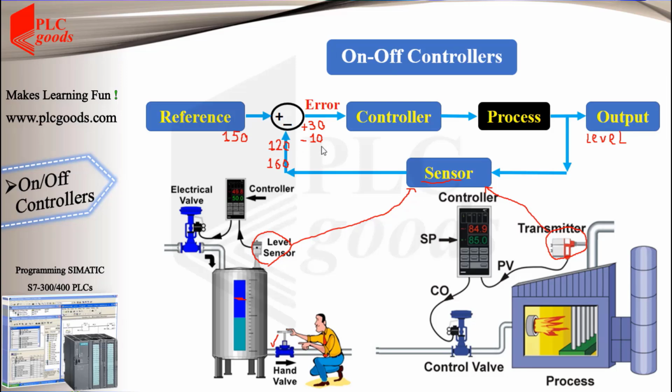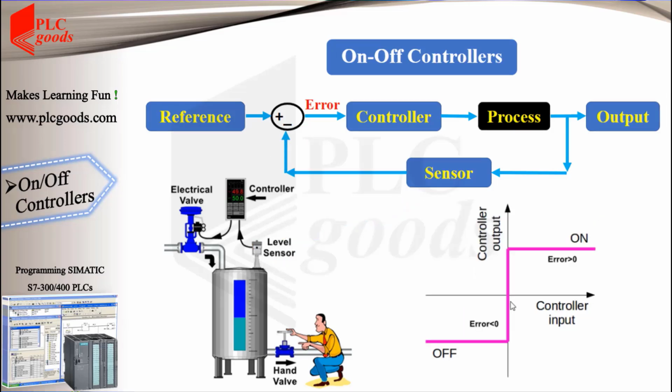Remember that we implemented an on-off controller to control the water level in a tank. In that case, by using the PLC as an on-off controller, we noticed that anytime the water level reached the desired level and the error value equaled 0, because of some fluctuation in the water level, the PLC started turning the inlet valve on and off continuously, which increased the fluctuation.